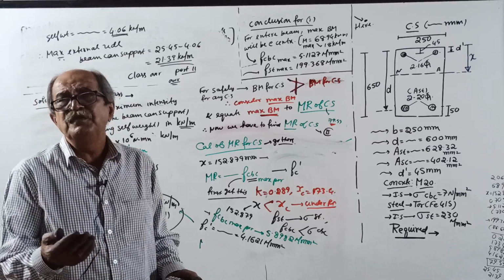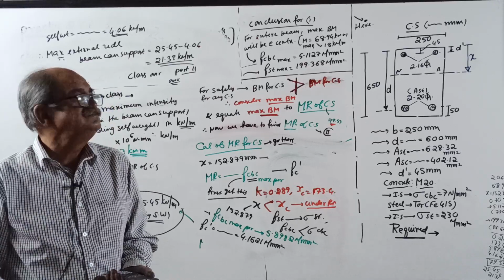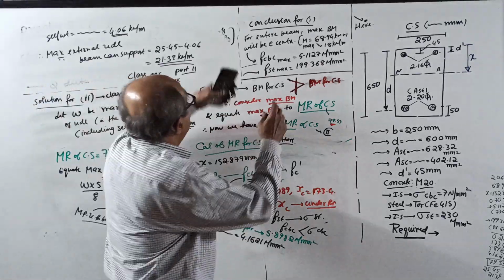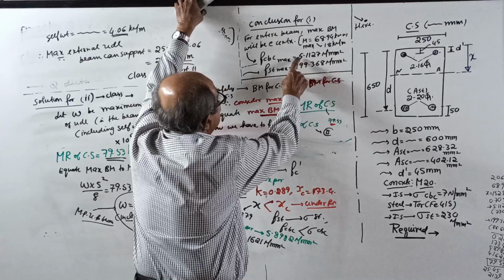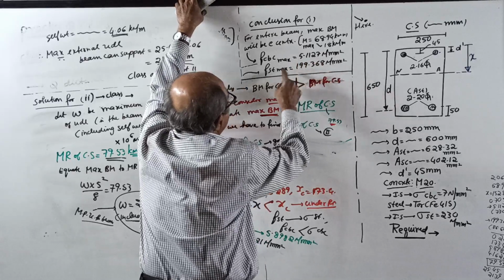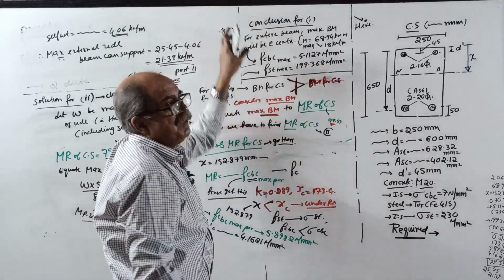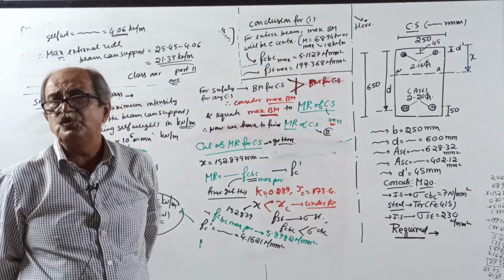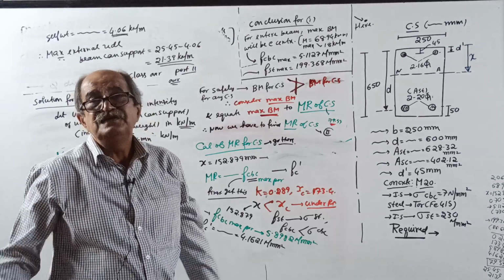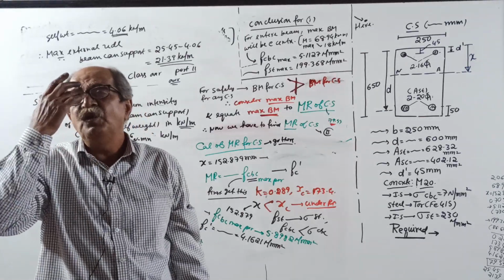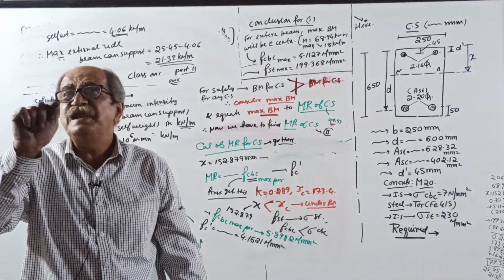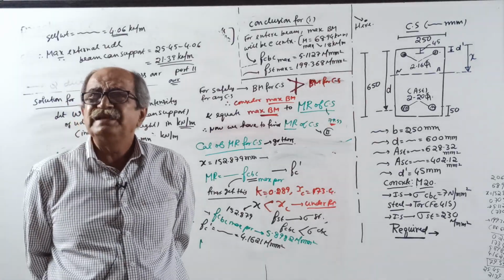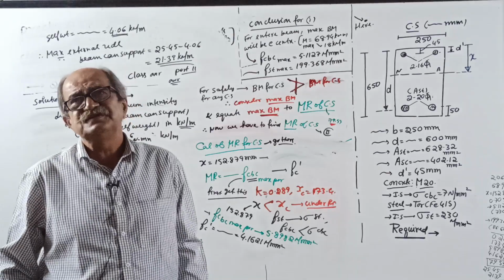Okay, I will tell him, give me a small paper. I don't have to write everything. Calculation required. I will finally tell him the answer. Maximum stress in concrete, 5.1127. FST maximum, 199.368. Okay, he told, yes, correct. Maybe he has got the solution. Then he will ask me, I told you, the beam is loaded by an external UDL of 18 kN per meter. Can you tell me what is the maximum UDL the beam can support? Yes, calculate.